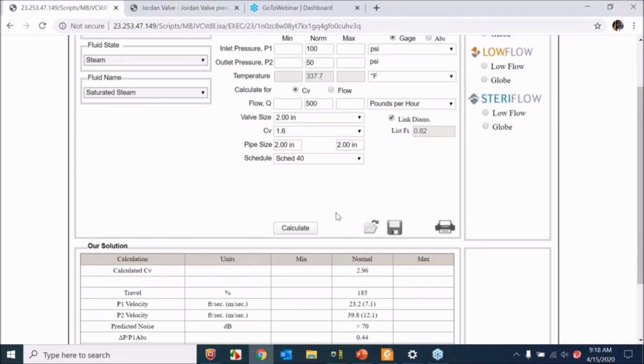So this is basically going to pinch off or choke the flow coming out. So instead of having 500 pounds per hour, it's going to be 300 or 400, whatever that number calculation we can do to figure that out. So the flow to that piece of equipment is not going to get there if we undersize a CV.